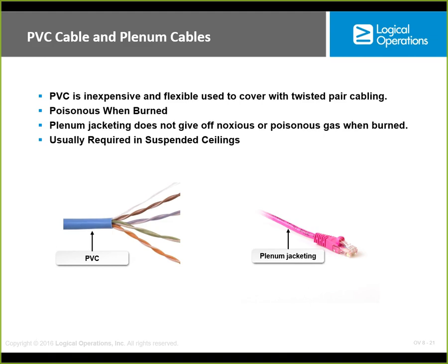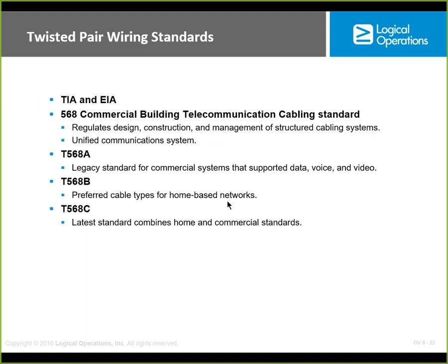Actually it probably is the only one that you should use any place, but if you put it in a suspended ceiling or in a plenum, an air space of any kind, you need to use Plenum cable, and it'll be marked on the cable itself. It'll say Plenum on it, so there won't be any question about it. This one here doesn't show any markings, but you can see on the pink one here there are some markings on it, and it will have what kind it is, what category it is, whether it's Plenum, and if it's on a reel, it'll have foot markings on it showing how much of it you have used.